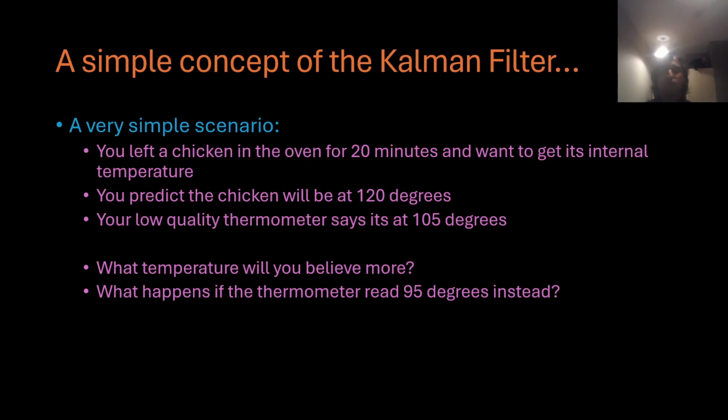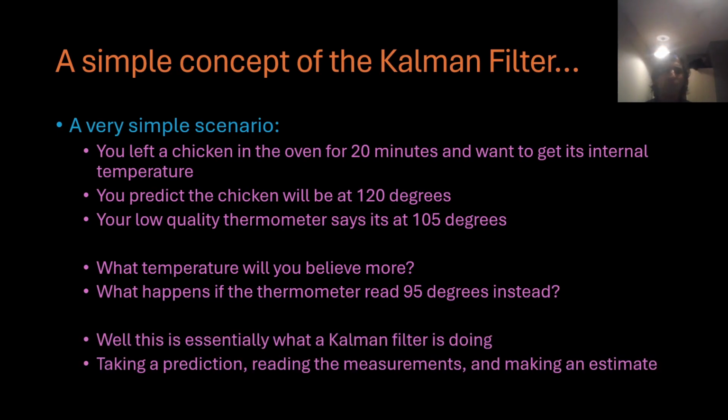What happens if the thermometer reads 95 degrees instead? But remember, this thermometer is low quality, or maybe it's really old and can't do its job properly. So who are you going to believe? Are you going to believe this 120 degrees prediction that you made, or will you believe the 95 degrees on this low quality thermometer? And essentially, that's what a Kalman filter has to do. It's taking a prediction, reading the measurements, and making an estimation.